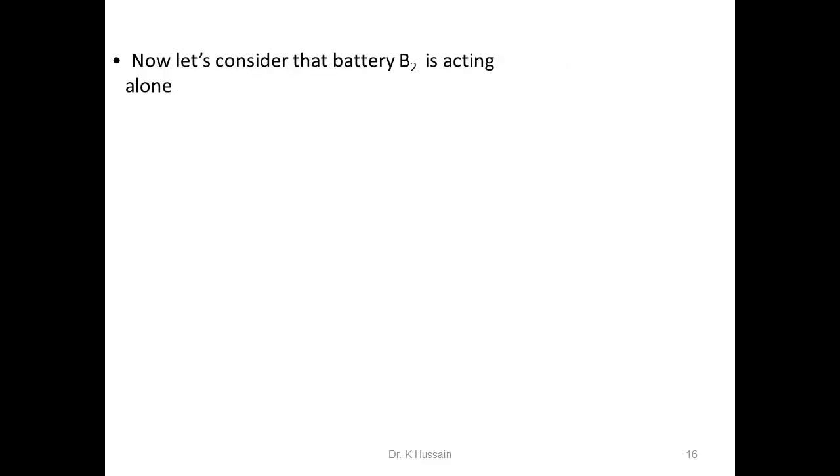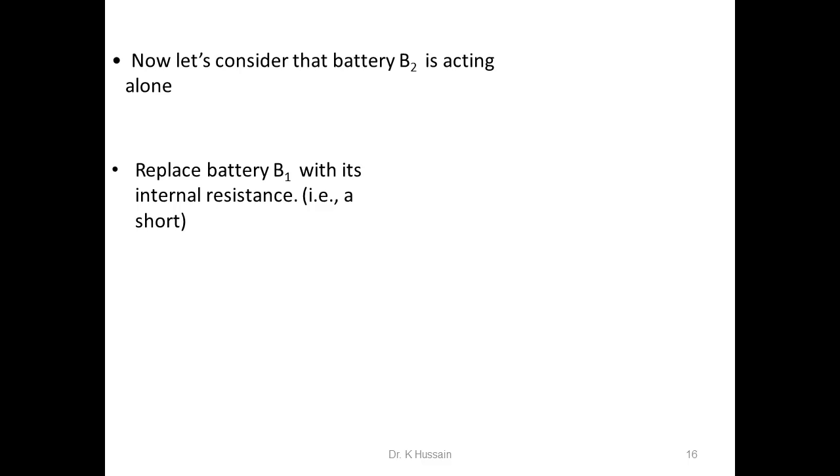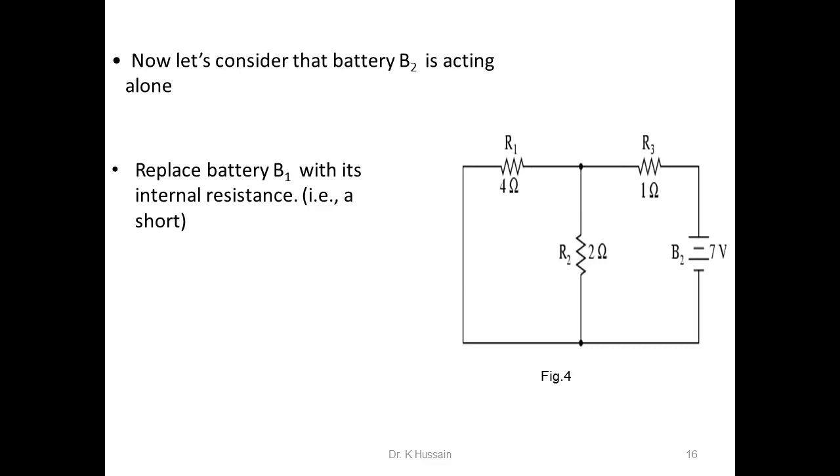Now we'll see the second case. In this case again only one source is acting, that is V2. Okay, V2 is acting, so V1 should be short circuited. Now you see, only the V2 source is acting. This is the source V2, right? Now this is which one? The V1 source, actually it is a voltage source. So when the second source is acting, at that time it should be short circuited. Here S/C means short circuit. In short form I am writing S/C, short circuit.